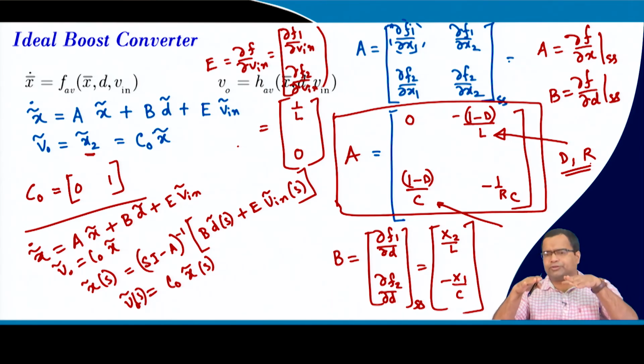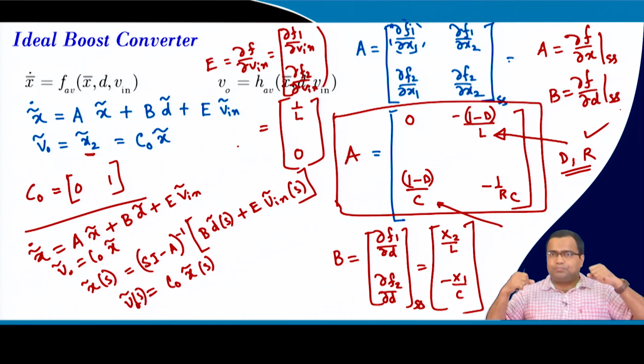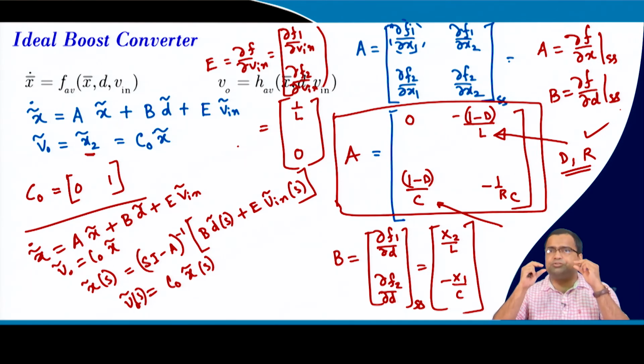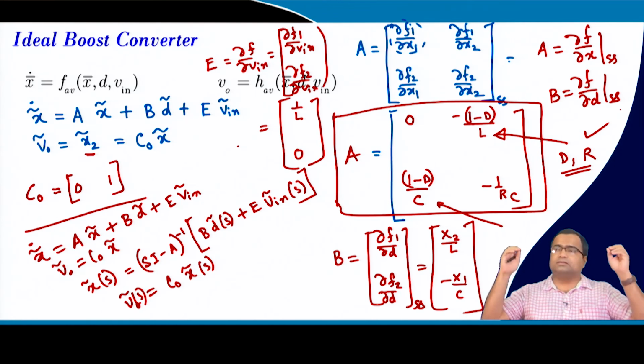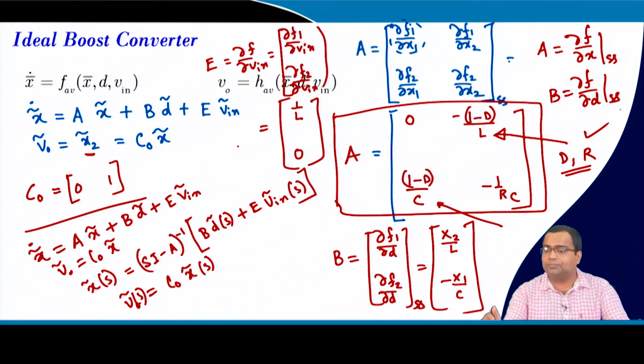This is the operating point, that means the duty ratio will vary based on your input-output voltage relationship. Even for a practical converter, if there is a load transient, R will definitely vary, and in addition there will be variation of duty ratio, because the practical duty ratio will be slightly different from ideal. In order to anticipate that additional drop due to the finite DC output impedance, you need to increase it. Suppose there is a load step-up transient, your effective duty ratio has to be slightly higher than the ideal duty ratio to get the desired output voltage.